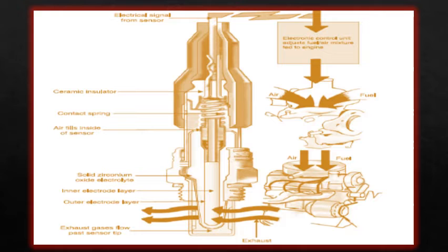Fuel injection systems have been using microprocessors for some years, originally varying the mixture only according to the engine speed and throttle setting. Many systems now include sensors for monitoring such things as engine temperature, air pressure, and so on. More recently, the German manufacturer Bosch introduced a lambda sensor to detect the amount of oxygen in the exhaust. It works by checking the electrical conductivity of the exhaust gas. Any deviation from the set limit can then be corrected by altering the fuel injection via the microprocessor.